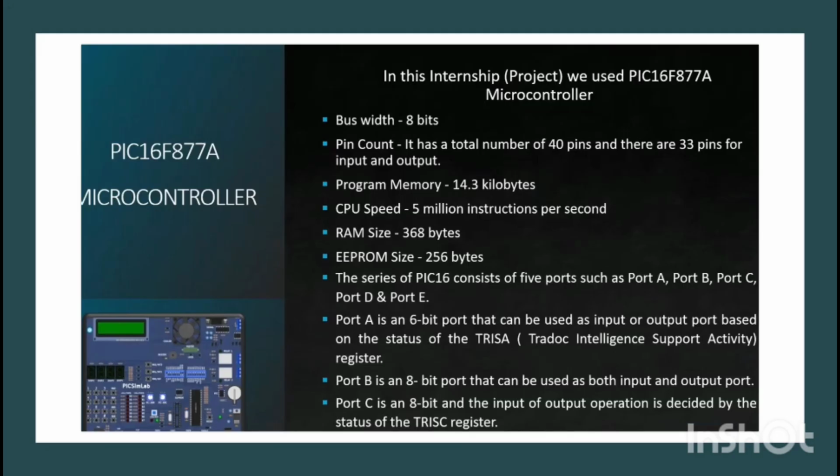Here we can see the microcontroller. In this internship we used the PIC16F877A. Bus width is 8 bits. It has 40 pins, and there are 33 input and output pins, and the program memory is 14.3 kilobytes. The CPU speed is 5 million instructions per second, and the RAM size is 368 bytes.